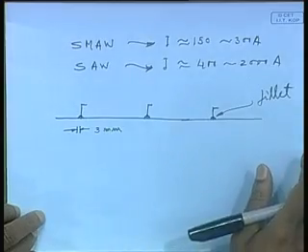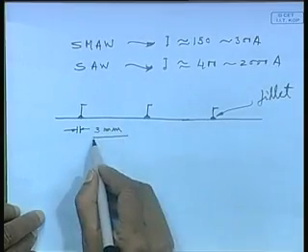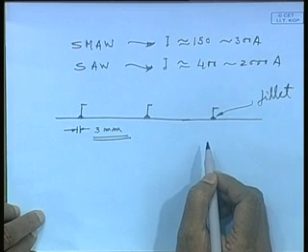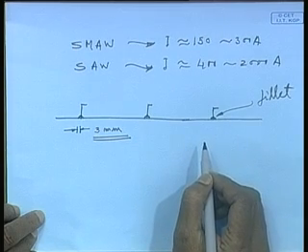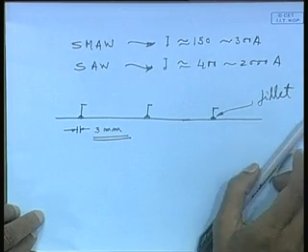If we do more, not necessarily it makes the structure stronger or any other thing, but definitely it does harm as far as distortion is concerned. More heat goes into, so more deformation, more thermal stresses, more possibility of residual stresses, right. So, you will have to look for such welding processes wherein you can control it to the desired dimensions of welding. So, fundamentally no over welding.